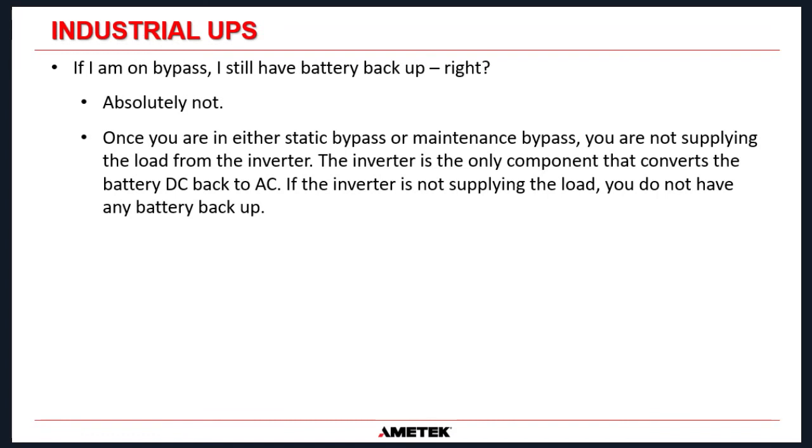So think about that for a moment. If you're on bypass, you're not supplying the load from the inverter. The inverter is the only component that converts the battery DC back to AC. So if the inverter is not supplying the load, you don't have any battery backup.